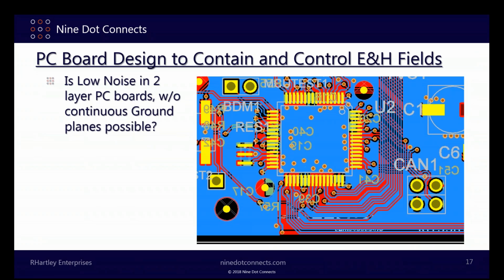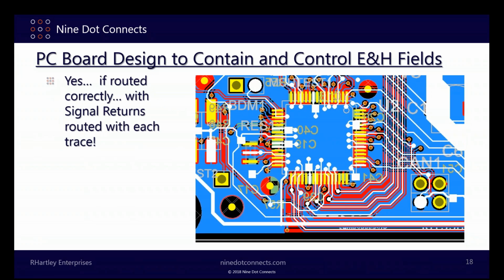What about a 2-layer board? If we have routed traces on both sides of the board without a plane anywhere other than poured copper on the surface layers, what's going to happen here? Well, obviously, this looks like the same thing we just looked at. We're routing multiple signals across splits in the layer below. This is a bad plan. What I haven't shown you thus far in this picture is that some of these traces, all the ones highlighted in white, are ground traces.